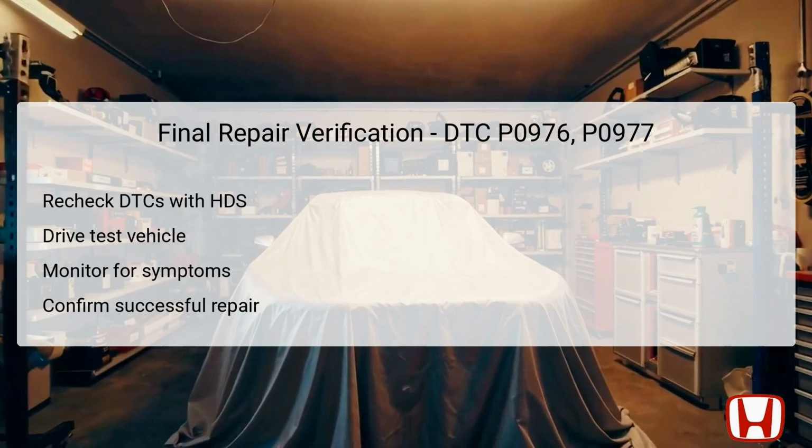After completing the corrective actions for DTC P0976 and P0977, it's essential to verify that the repairs were successful. Use the Honda Diagnostic System, or HDS, once again to check for any remaining DTCs.